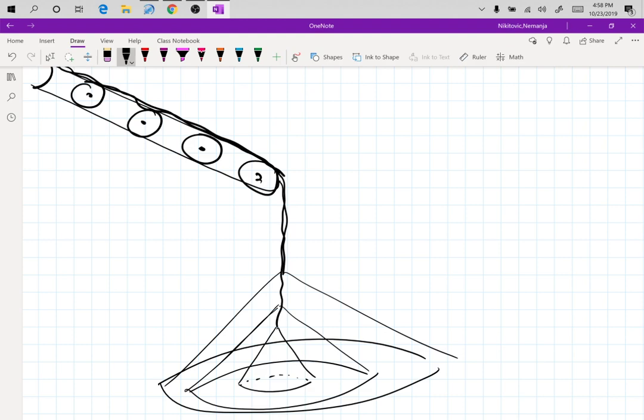So now you have to design a shut-off switch, because you can't really use, in these conditions, photo sensors or infrared sensors or anything like that, because there's a lot of dust. There's a lot of dust in these quarries and farms and so on. So the sensors get quickly dirty and dusty, and then they don't work, because the sensors of that kind work on being interrupted. And obviously, as soon as they get dirty, they get interrupted. So you can't use those.